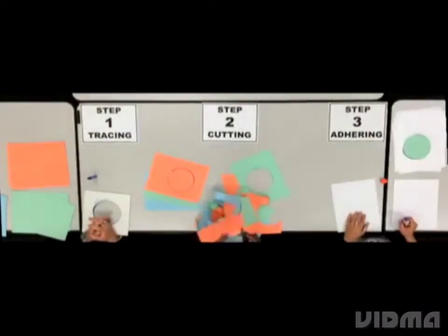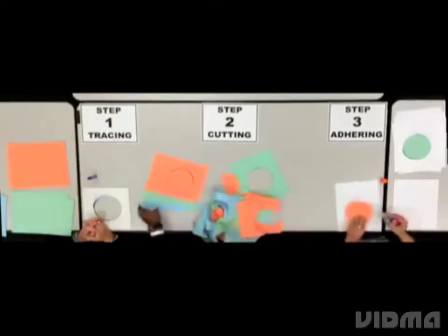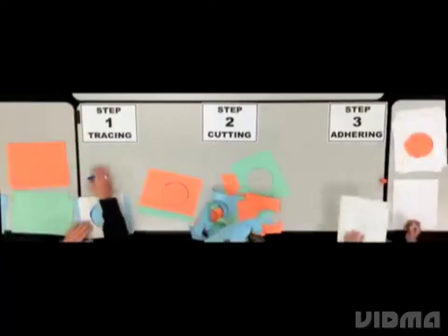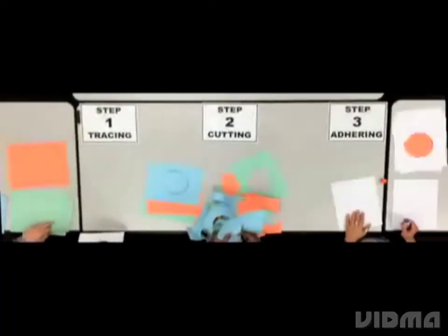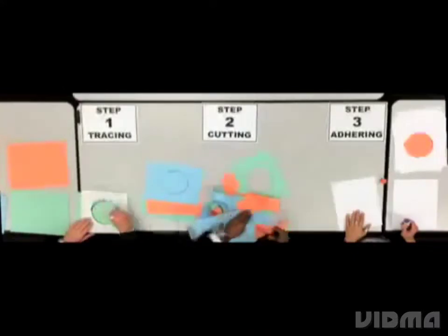When we measure the cycle time, we get roughly 13 seconds. Do these times meet our takt time? Yes, they do. If we continue to run at this pace, we will meet our customers' demands. Now, let's evaluate the cycle times of the individual process steps with enough inventory to let them run.